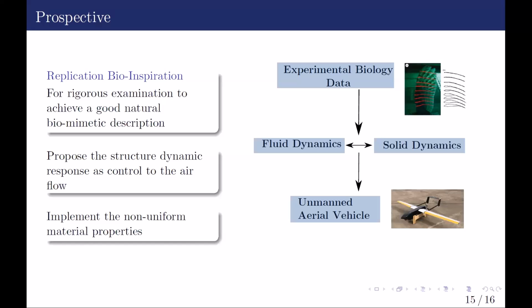Okay, not a question, but just a comment. When you're setting your material properties, you don't need to use swak4Foam. You can use expressionSetField, which has been put in like four versions ago. ExpressionSetField, and you can give an expression to set your fields for non-uniformity. You can implement like an expression function.